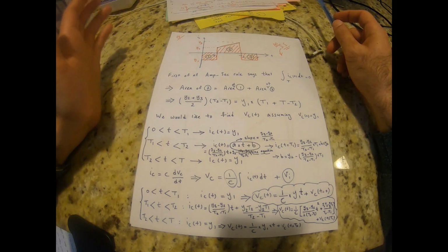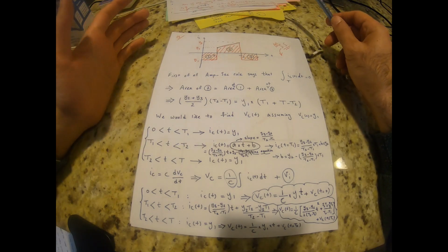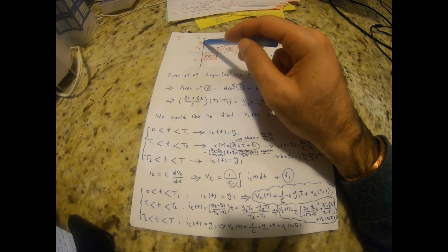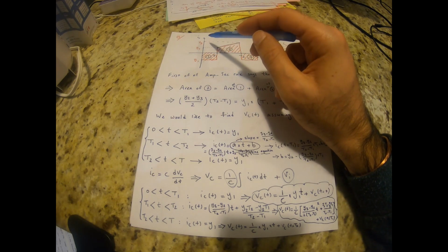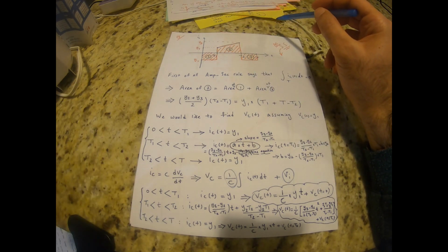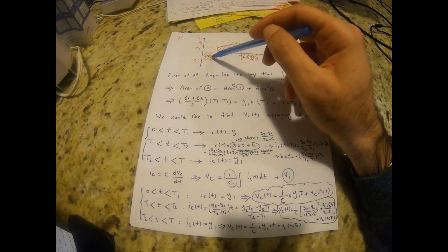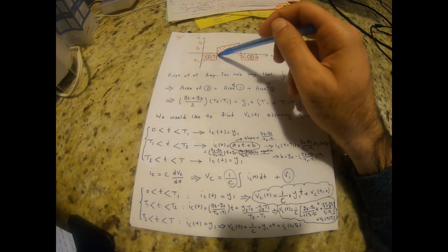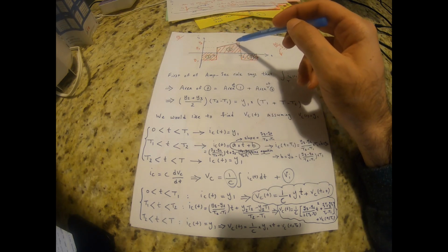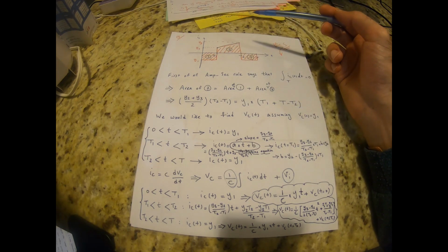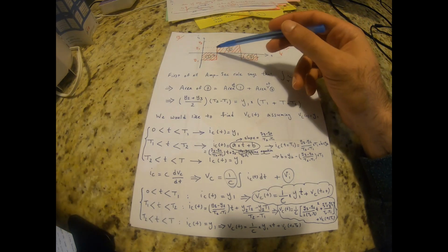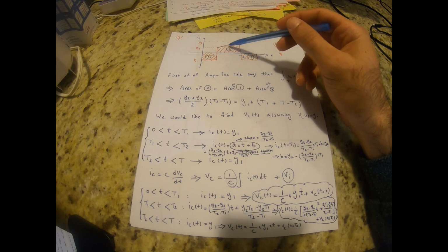Why is that the case? What's the physical meaning of that? It means that if a capacitor wants to be in the steady state, then the charge it gets during a period and the charge it loses within that period should basically match. If this much current goes out of the capacitor, then to end up in the steady state, you're not supposed to add any more energy to it. So you basically have to provide the same amount of charge or energy.